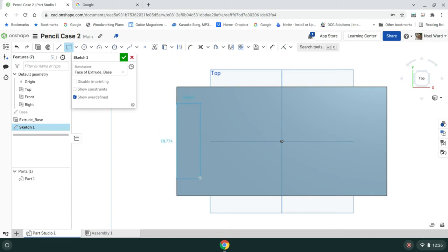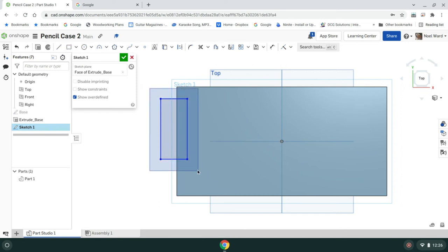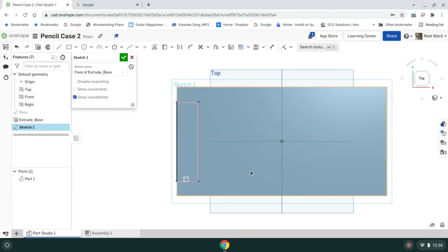line. If it's not on that line, and maybe what I should do is show you, if I draw this wrong, what I can do is I can click and highlight this and delete it, backspace, and I'll show you if it was done wrong, it's not on the line. So that'll be no good to me. I hit escape again and then just draw this over it, backspace. So just make sure that you're picking your corner rectangle right on the line, and we'll draw it down. When you see that wee coincident thing, that lets you know that it is on that.